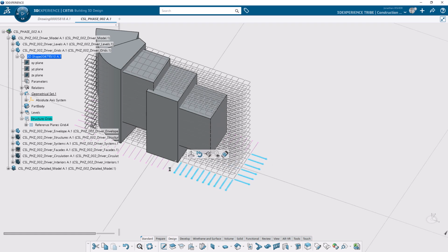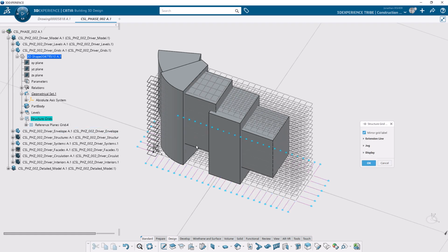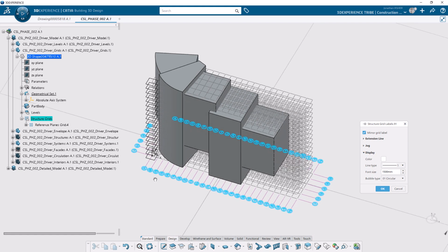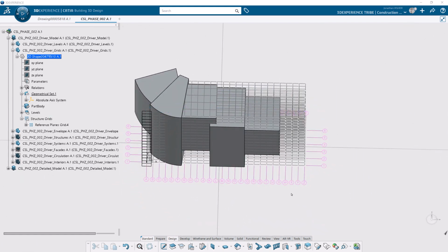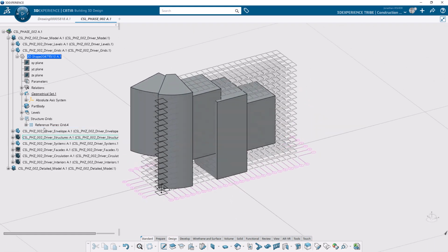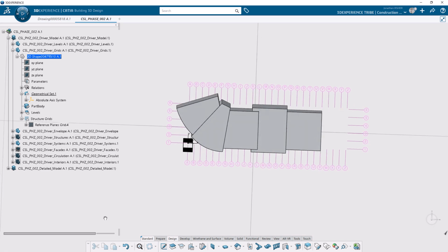It automatically does create the labels for you. And in this case, I'm going to make them a little larger so they're easier to see. I could have done a select of these labels in the tree, and that might have gone a little faster, but instead I clicked one by one. Then do a multi-edit, and we'll change the size of the display font here to 1500. What you see is what you get in terms of the size of these grid labels.